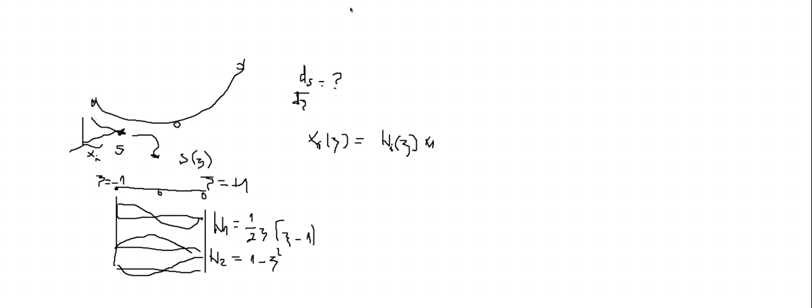That means basically I can have this one for x, for y, and for z. Just taking the coordinates of these nodes 1, 2, and 3 for x1 and for the direction x, direction y, direction z. Then what I can do here, I can take this to be a square root of (dx/dxi) squared.